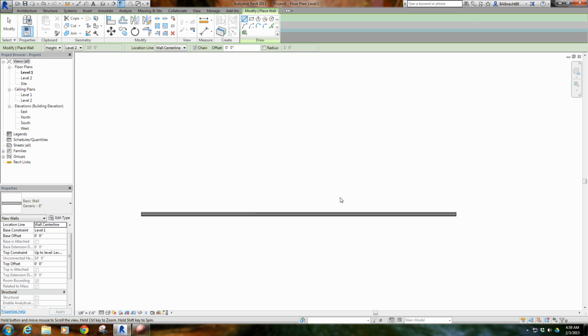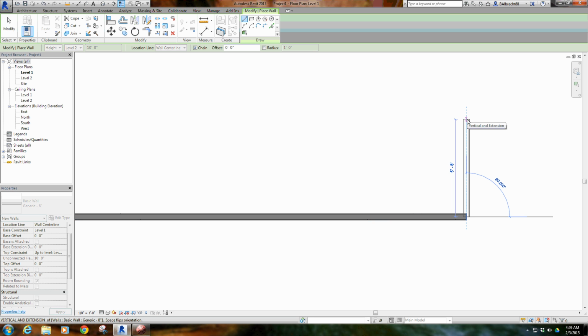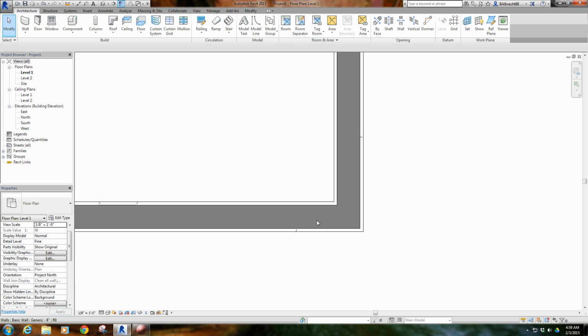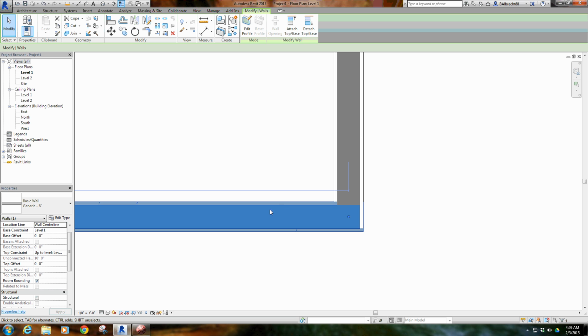And now if I create a wall, every time I draw that, it's going to show me all three of those layers. So when I do a connection, what I meant by wraps is if I click on this, you can see that it's taking this wall and this wall is continuing on. It's not mitering the corner. When you frame stuff out, very, very rarely do you actually miter your corners. So this is going to butt into this, and what that wraps means is that these finishes, so the gypboard, is going to wrap the end here. So it's going to fill this end cap with the gypboard as opposed to just leaving it open for the stud.